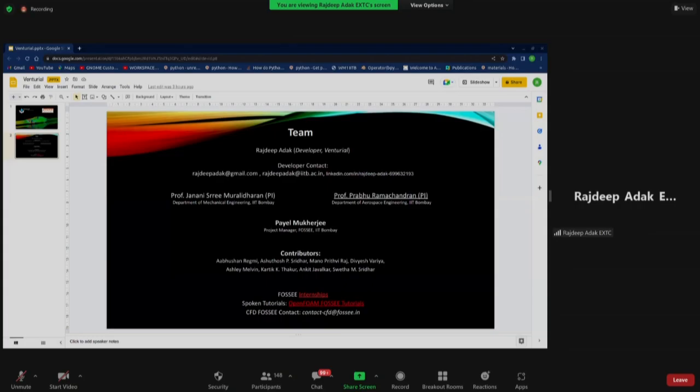So in those, you can even do curve geometries. You can actually create meshes out of it. Actually, we face a problem here: meshing. Meshing is the thing. We will have refinement zones based on the inflow velocity and y plus values. Sometimes we will not get it in a single go, and our solution will not converge. So meshing is the main problem we face here. Once meshing is proper, then the solution will go.